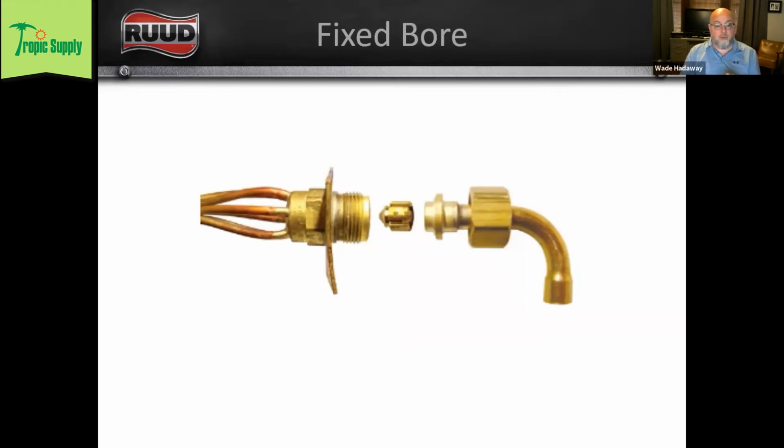Do we have superheat? And then checking it again just to see how much extra heat we're picking up. We're not going to charge based on superheat, but we are going to look at it and make sure that it's present. It looks like there's another question.